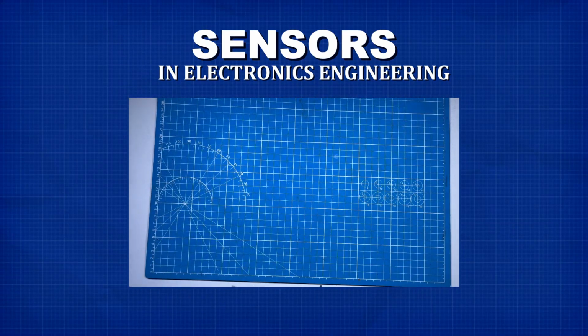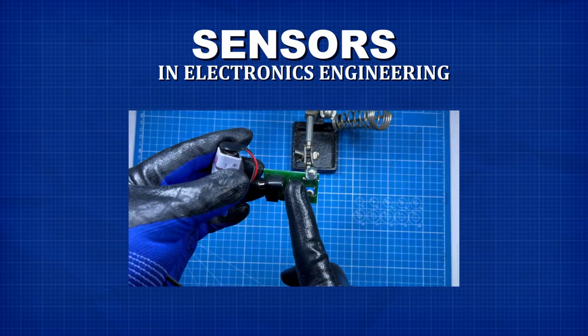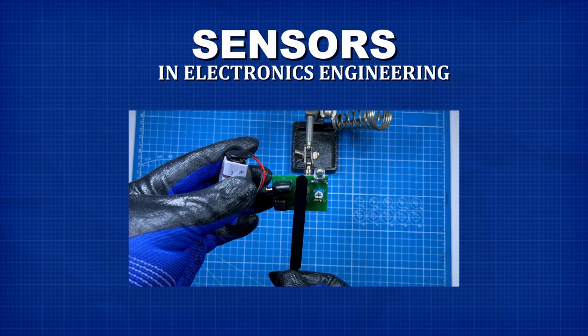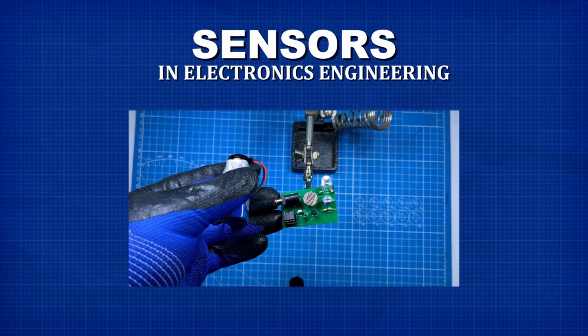Now after placing and soldering the components on the PCB, let's test the circuit. When light falls on the LDR, the lamp stays off. But immediately I block the light and make the environment dark, the lamp turns on automatically, and that is how an automatic darkness sensor circuit works.